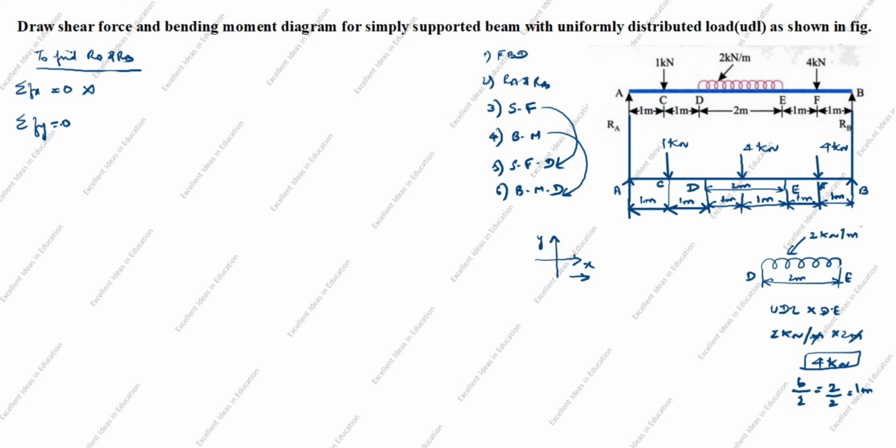You see this graph, y is in vertical. We will take arrows goes up is positive. RA, this is RB. You see the RA reaction force arrow goes up. You see up is positive. We will write RA. You see this load, arrow comes down. So down is negative, negative 1.